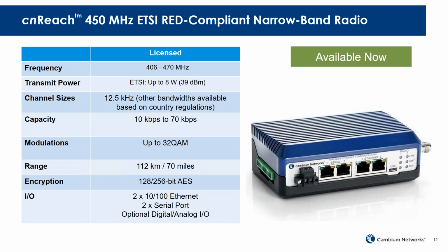The Red initiative went into effect, the final deadline was June of last year. We made some changes to the radio, and there's 2 major benefits here. One is this radio now covers 406 to 470 inclusive. So it covers that complete band from 406 to 470. You'll remember in FCC bands, we cover 406 to 430 and 450 to 470. So there's that gap between 430 and 450.